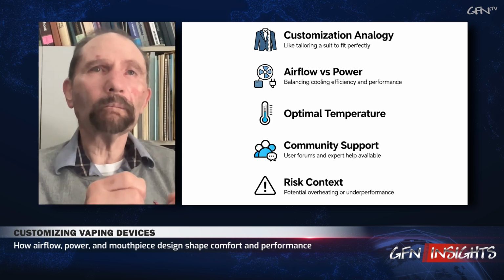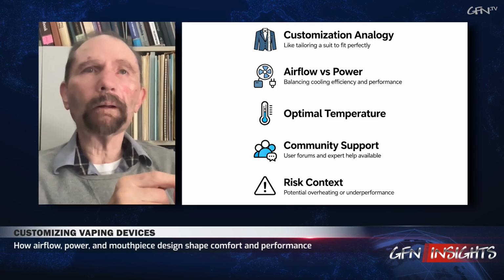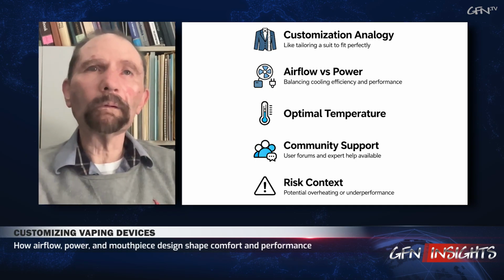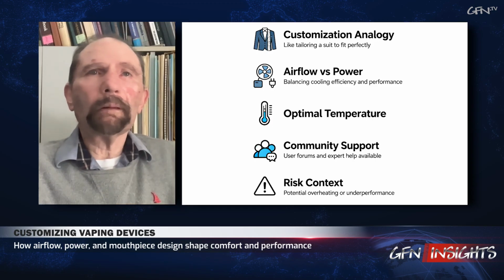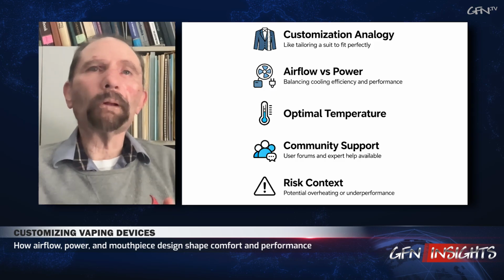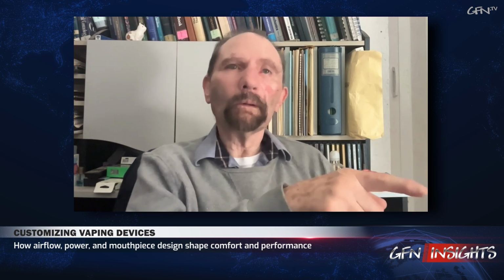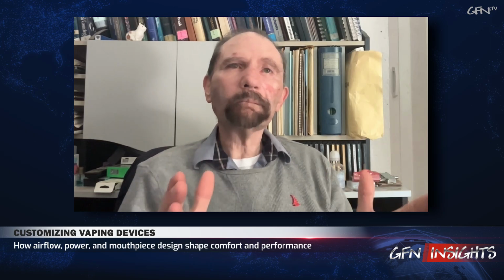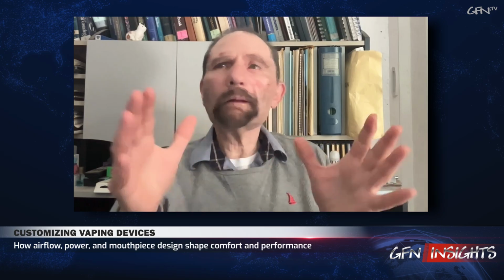There are forums, there are magazines, but essentially users can customize it on their own. And each time they customize it, they alter a physical parameter. And if they customize it well, the thermal cycle will be efficient with little residual energy, and vaping will be enjoyable. It stops being enjoyable when you alter the chemistry because of overheating, right? And that has to do with the temperature dependence of the reactions. If you are in the optimal regime, the reactions are weak and the taste is okay.